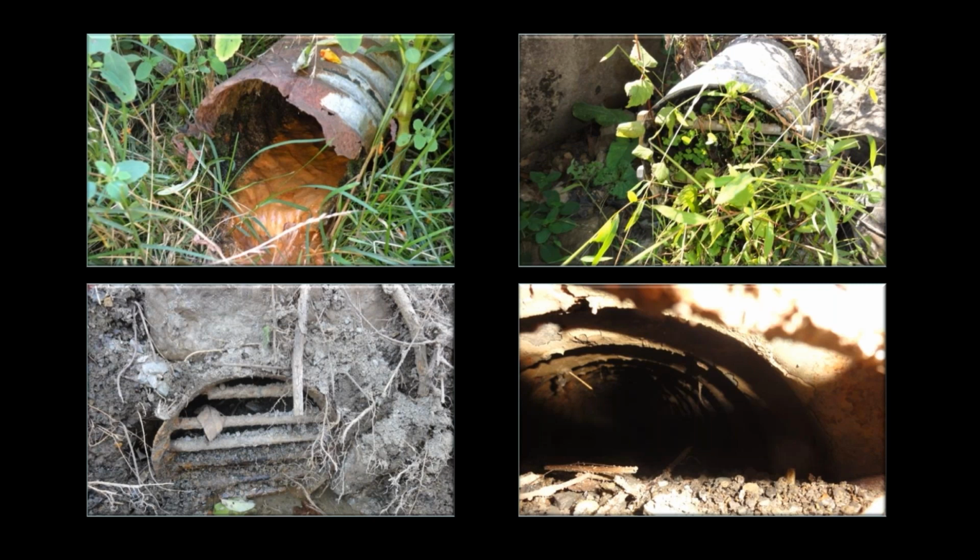Unfortunately, most of the dams that were built with this type of drain pipe do not have that feature. And if a dam is being rehabilitated, that's something that's often addressed at that point as part of the rehabilitation. But many dams are not. So when you're inspecting a dam and it has this feature, some of the things you may see are little sinkholes along the toe of the dam where the drains have collapsed, which is an indication that they may not be functional anymore either, because they could be obstructed.